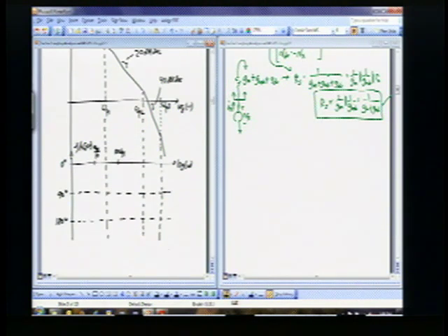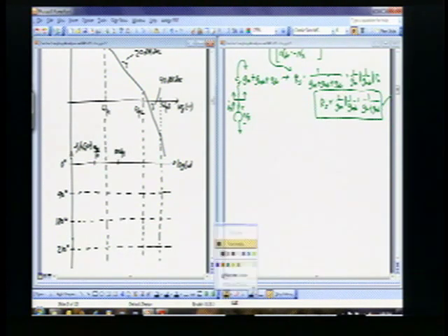And I can keep going here, which I will for completeness, 270 degrees there. Okay, so you sort of plot out these asymptotes. And so what these omega p divided by 10 and omega p times 10 do is they tell you where those asymptotes should go. So I can draw something like this and like this, and I can draw a line from that point to that point, and that becomes the asymptote for my phase, which I'll draw in blue here.